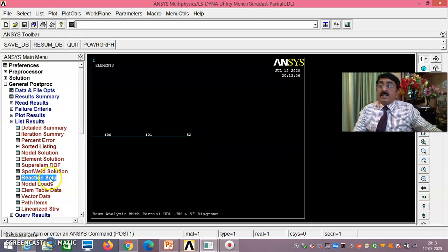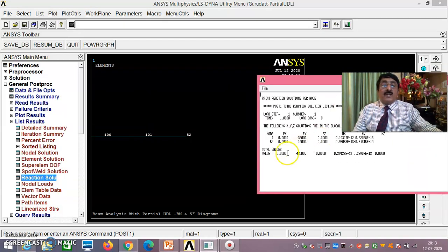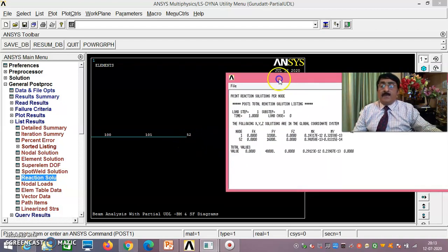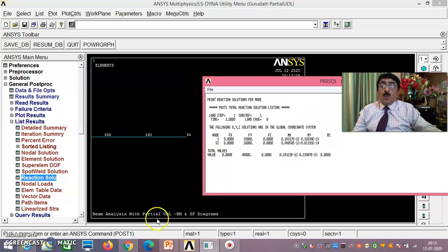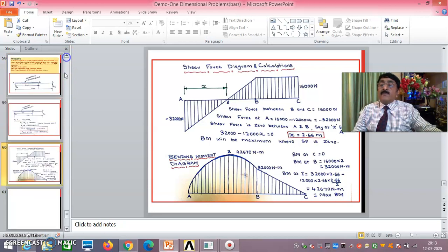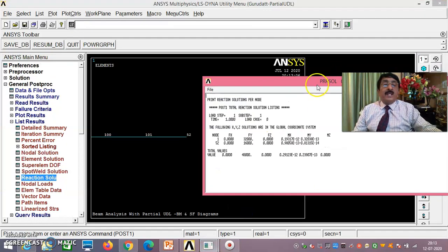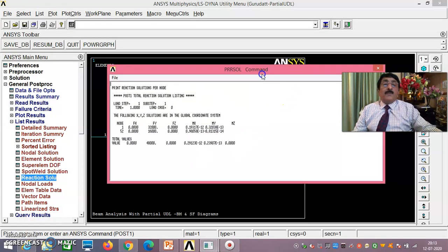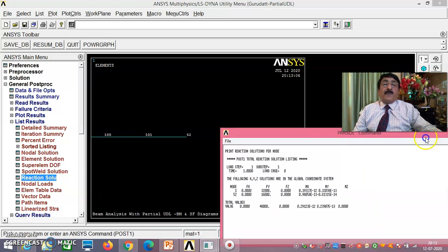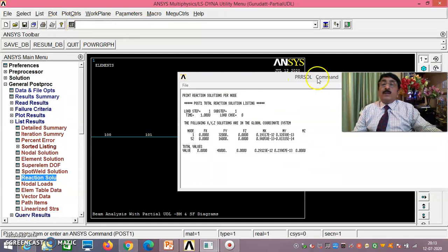Did you follow? List Results, Reaction Solution, All Items: if you do this, see carefully, first anyway is 32,000, and at 52 it is 16,000, exactly matching the results we got using theoretical methods, as I just now told you. 32,000 and 16,000. In that way, we have completed the problem on the partially applied UDL.